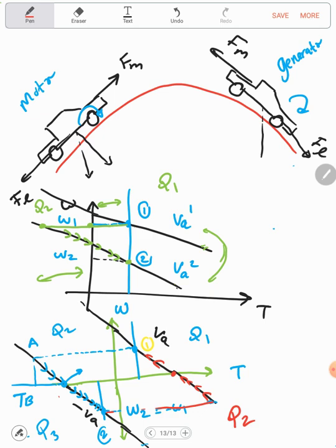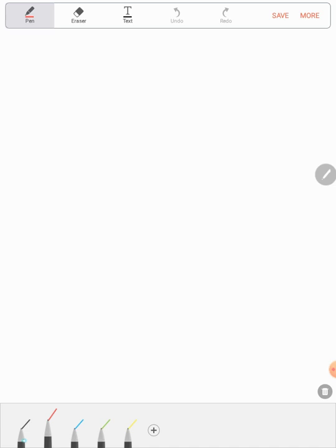So sometime we can use this method in order to dynamic brake the machine. In the dynamic braking, it's similar to the regenerative braking, but the supply is disconnected, and sometimes we are placing external resistance in order to limit the braking current in order to protect the machine.